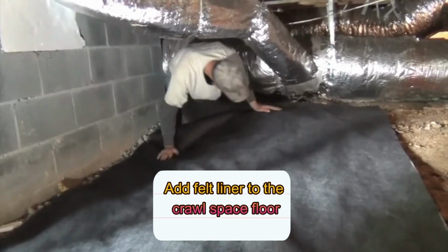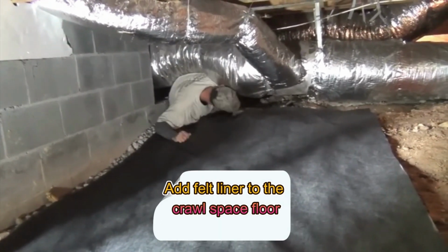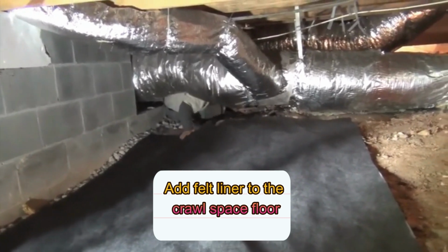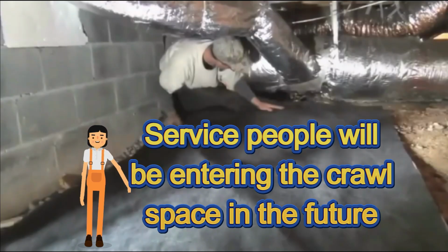Before we put down our vapor barrier, we need to lay down a felt liner on the floor of the crawl space. This adds another layer of protection to help keep the vapor barrier from being punctured. You have to keep in mind that service people will have to enter the crawl space from time to time, and the barrier needs to hold up for the long run.